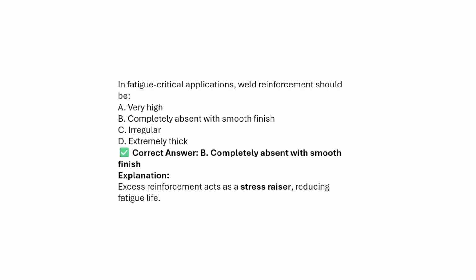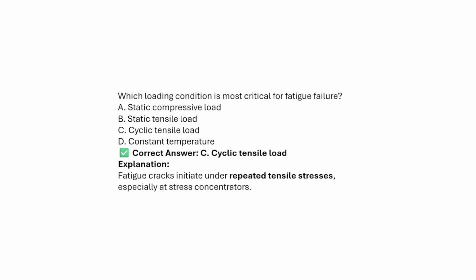In fatigue critical applications, the weld reinforcement should be: option A, very high; option B, completely absent with smooth finish; option C, irregular; option D, extremely thick. So the answer will be completely absent with smooth finish. Excessive reinforcement acts as a stress raiser and reduces the fatigue life.